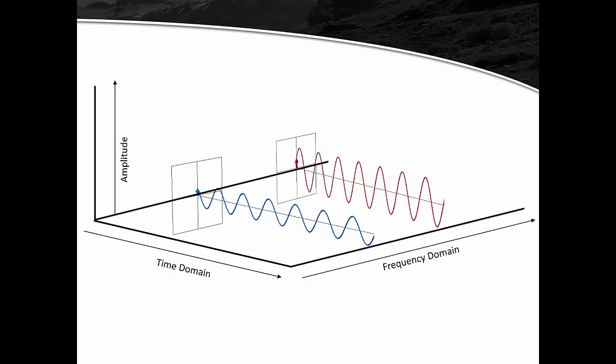We're looking at the wave, if you can think of it this way, like it's coming right at you. You're looking at the specific frequency as if it's coming right at you. Whereas if you looked at an oscilloscope, you'd be looking at something more like the time domain. And you might think of this as the wave if it's passing by you. So the time domain, the wave passing by you; the frequency domain, the wave coming at you. And you're simply getting spikes for the frequency to show you the energy level of that frequency.